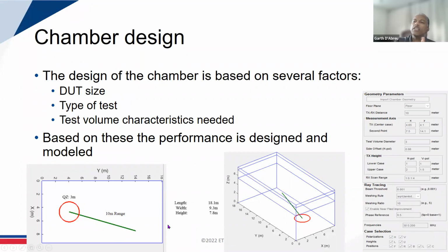I think across the industry, the design and operation of EMC chambers is very well understood. Just about anybody can build a shielded room with any sort of shielding material, from thick foils all the way up to thin sheets of metal with supporting structure. There are all sorts of RF absorbing materials that are available, and there are all sorts of techniques available for modeling and predicting the performance of these facilities.